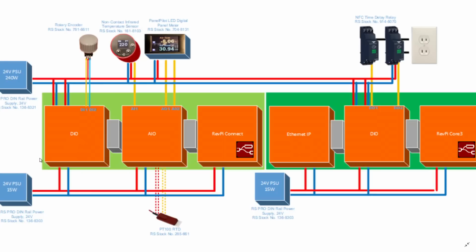I also want to be able to keep isolation between the I/O outputs, the physical I/O, and the control logic, so that if I did make a mistake up here, I'm not going to take out one of the controllers or anything like that. It also keeps noise crosstalk to a minimum and all that kind of stuff as well, especially if you're switching some higher current loads and things like that on this side of the power. So that's what we basically have set up here.